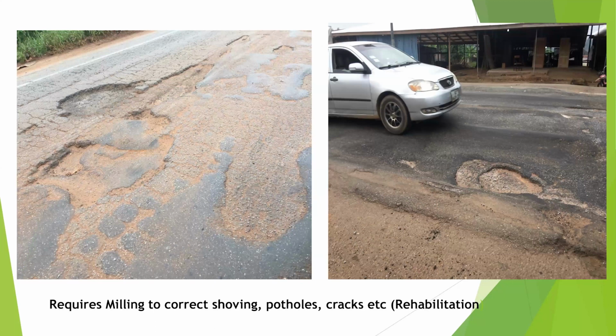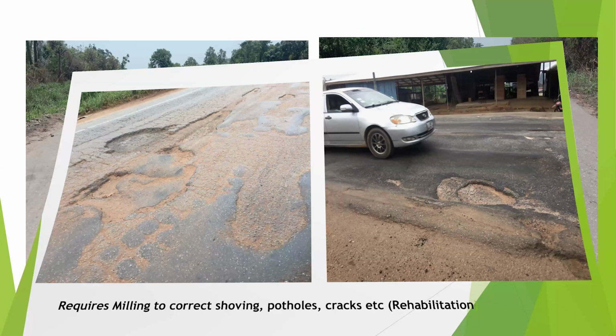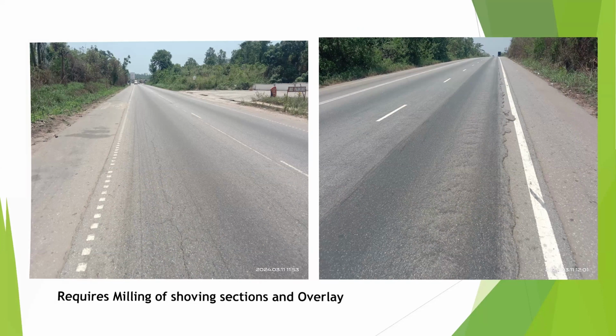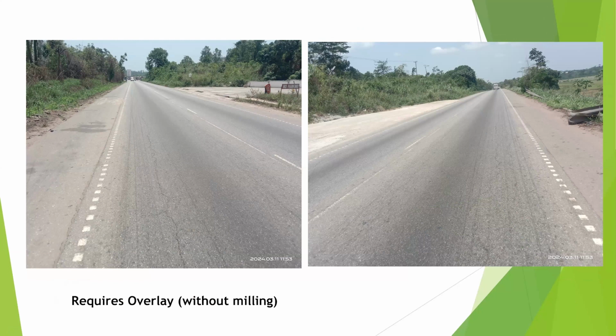Now, if you have this existing road surface, definitely resealing will not work. This is a typical Accra-Kumasi road. And so you have to do rehabilitation. And this is also the same Accra-Kumasi. And here, typically, you will have to mill some of the shoved areas and then apply your overlay. And so here, a combination of milling and overlay. This is purely overlay because you don't have shoving, it's only cracks. So you just apply the overlay straight away and then you are good to go.